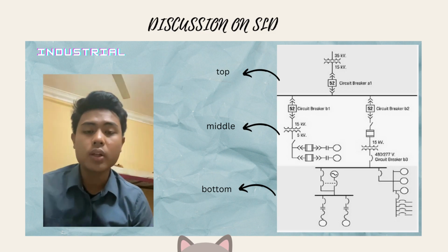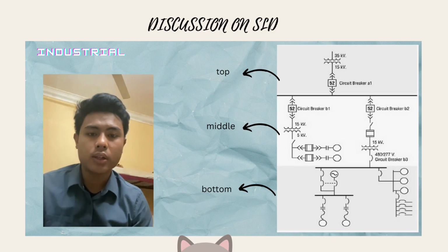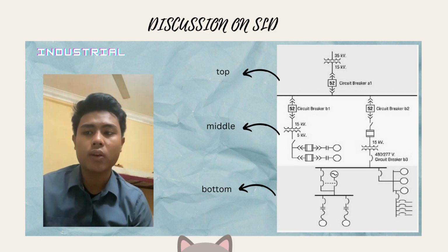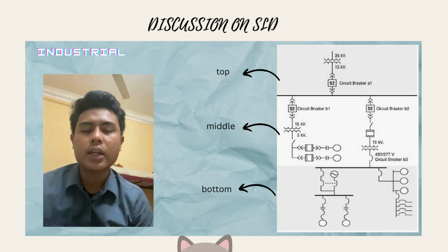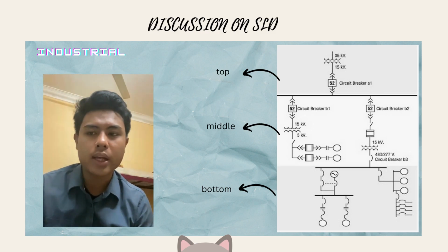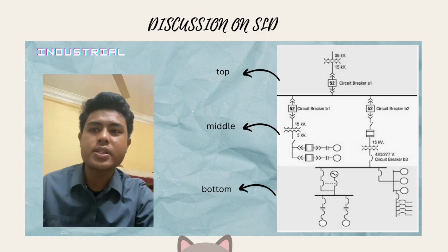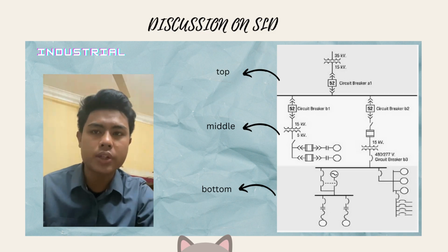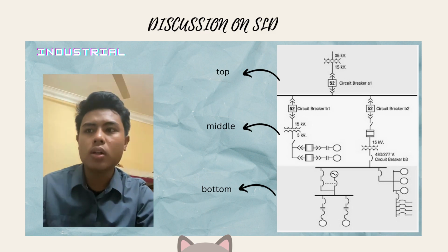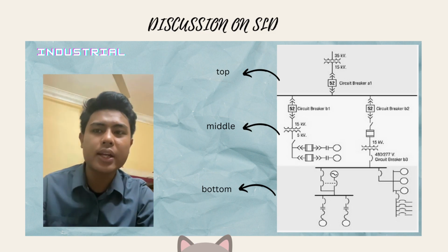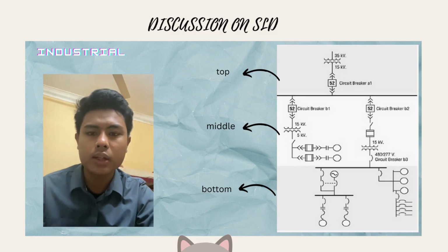After that, the transformer is used to step down the voltage from 15 kV to 5 kV. A disconnect switch is displayed on the transformer at 5 kV. The equipment isolated under the transformer connects using the disconnect switch and ends in the two medium voltage motor starters. The second draw-out circuit breaker is coupled to a step down transformer and a fuse disconnect switch. Due to the voltage being stepped down again to 600 volts or less, all equipment below the transformer is now regarded as low voltage equipment.